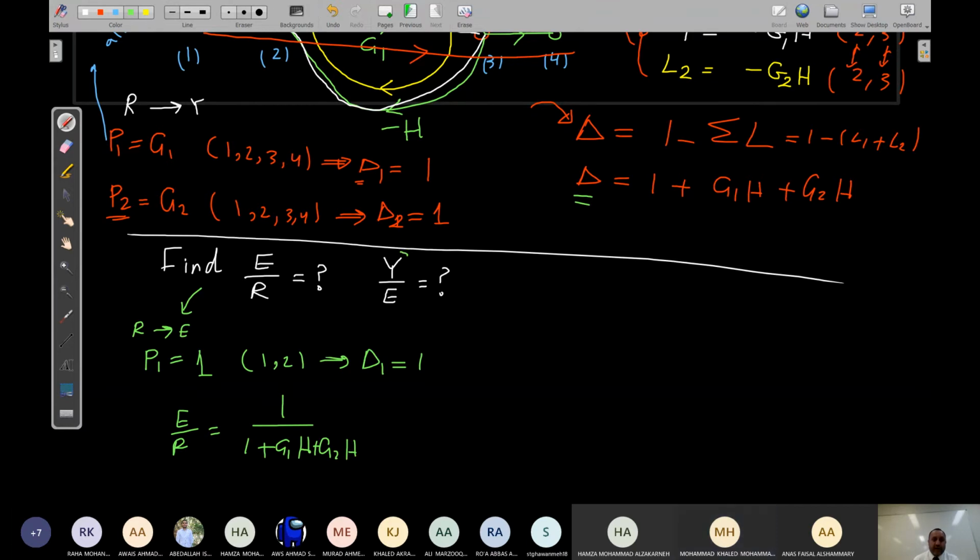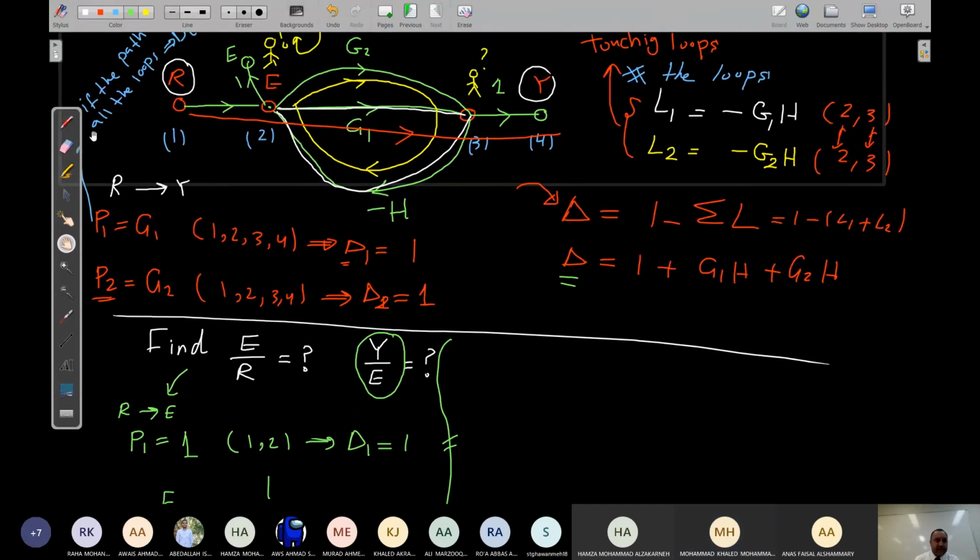Now, what about this one? Who can evaluate this one for me? Doctor, it will be G1 plus G2 over 1 plus G1H plus G2H. It will equal to what? G1 plus G2 over 1 plus G1H plus G2H. Who agrees with mine? Muhammad Hassan. Who agrees with Muhammad Hassan?